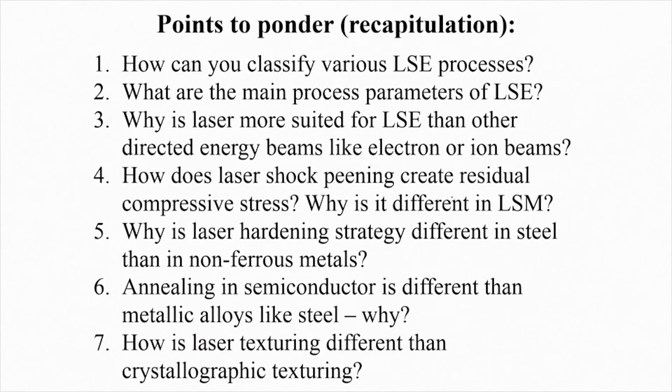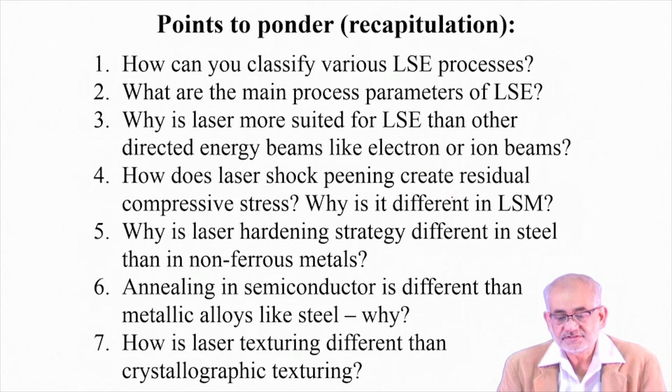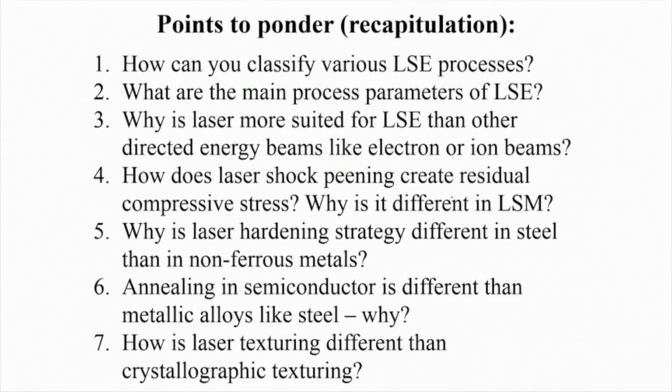In order to summarize, we can do various kinds of surface engineering using laser surface engineering, where either we change both the composition and microstructure, or we change only the microstructure and not the composition. That is possible very easily because we can control the heating rate, the heating process, and so on.